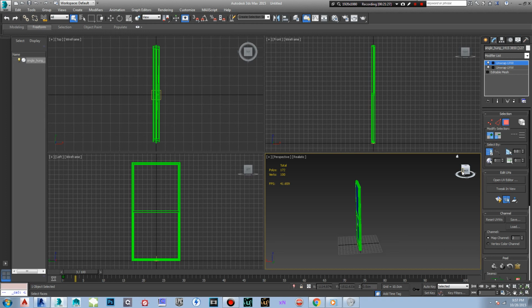Now, I would make a reference block, a BSP brush is what they call them, when you make blocks in Unreal Engine. It's sort of like making 3D models in the engine, but they're not as advanced as using 3ds Max or Maya. Anyway, you make a block, make it 183 units tall. When you make the block, make sure you raise it above the ground of whatever default map you open up, and then push the End button to make it drop right on top of the ground perfectly, so that from that point upward is 183 centimeters.